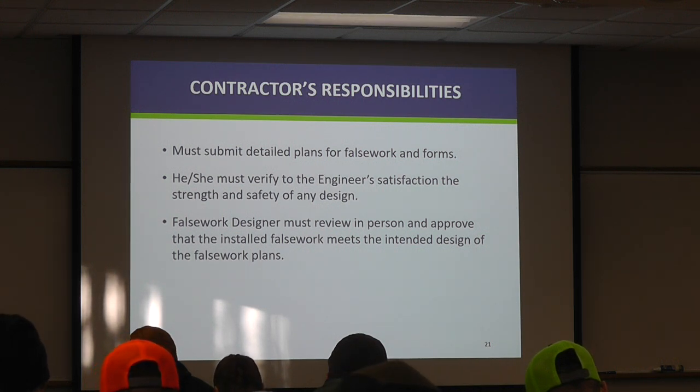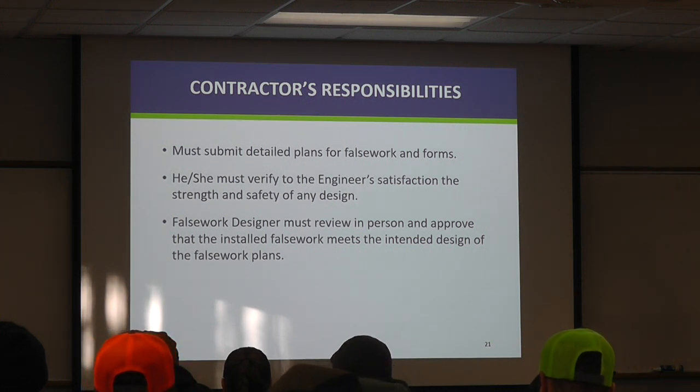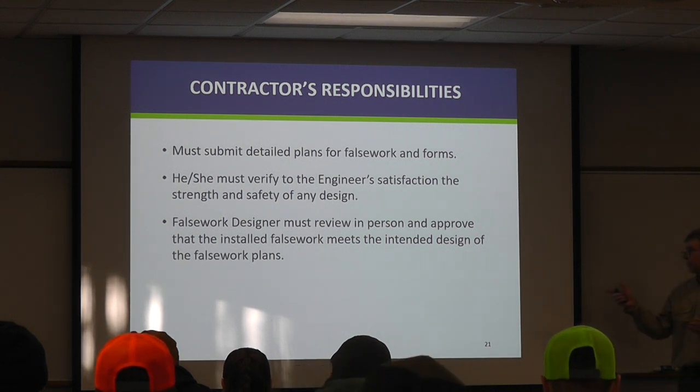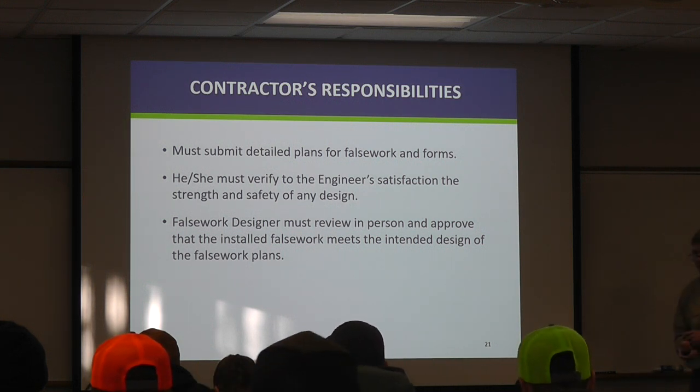Contractor's responsibility. Another key point is this third bullet. The falsework designer must review in person, meaning in the field, what that design was and approve that the installed falsework meets the intended design of the falsework plan.